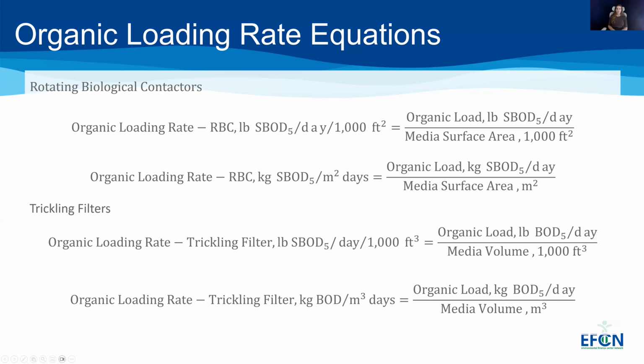A couple of examples of how to use those problems are going to be for RBCs. We'll have our organic loading rate, which is measured in pounds of BOD per day over the surface area, and that's going to be in thousands of square feet. Now, if it's trickling filters, this will typically be organic loading in pounds of BOD per day over the media volume in thousands of cubic feet. So, like I said, it sounds a little odd, but we'll show you guys how to do that.